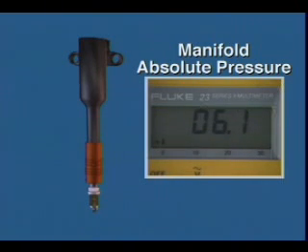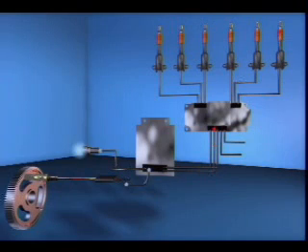At higher manifold pressures, the ECM reverts to normal 1 spark per cycle firing. When manifold pressure is falling, the ECM commands the ICM to deliver multiple spark discharge when pressure drops to 5 psi or less, and the ICM again fires the plug 3 times. The hysteresis, or difference in pressure to turn multiple spark discharge off and on, depending upon pressure increasing or decreasing, prevents switching in and out of multiple spark discharge repeatedly in the 5 to 7 psi manifold pressure operating range.